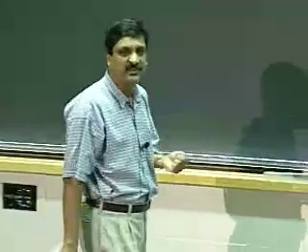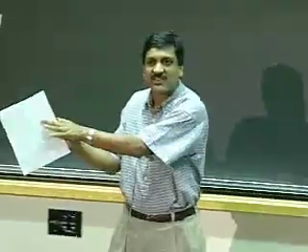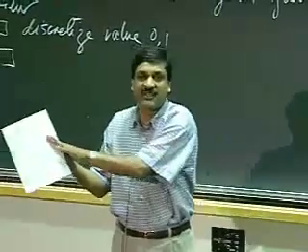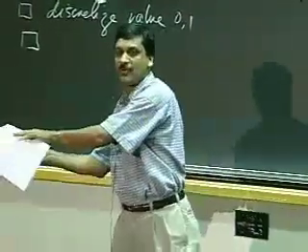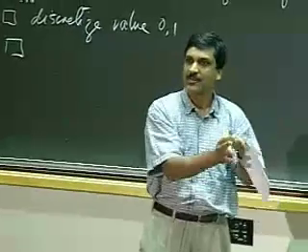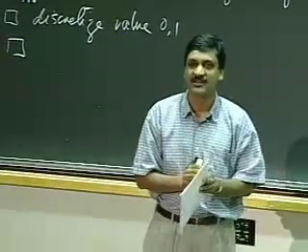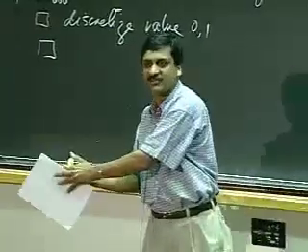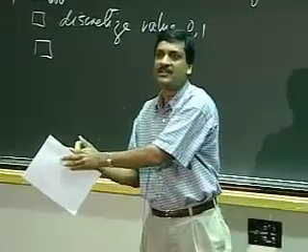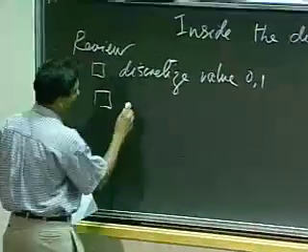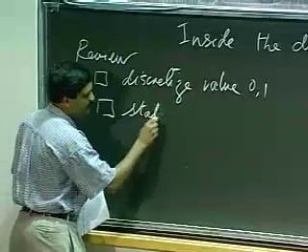We have to impose some constraints on ourselves. Just as with the lumped matter discipline, we imposed a couple of constraints in going from the continuous matter world to the lumped matter world. Similarly, we have to impose some discipline on ourselves, some constraints on ourselves in going from the continuous value regime to the digital value regime. And that discipline is called the static discipline.